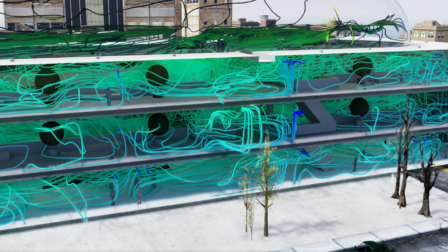So that passive scalar, we would track how it moves inside the domain and essentially assess the overall concentration and distribution of it. And adding that into the simulation is actually very easy. It's literally enabling one little setting. So it's basically 2 clicks max, and then you would be able to track the concentration.